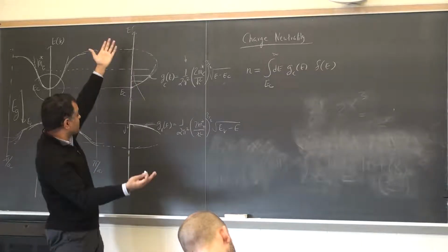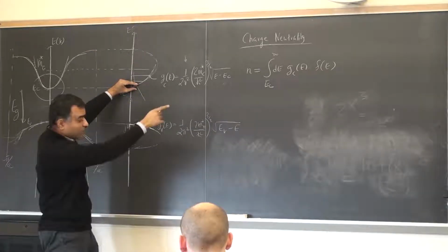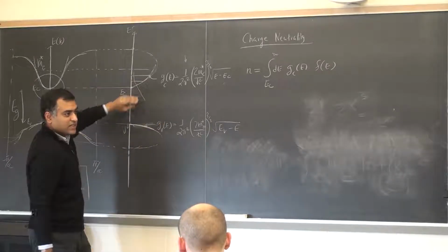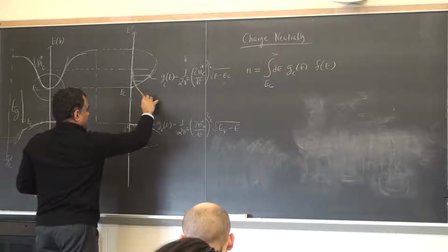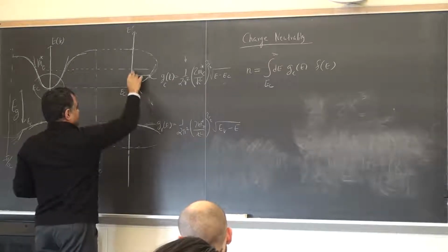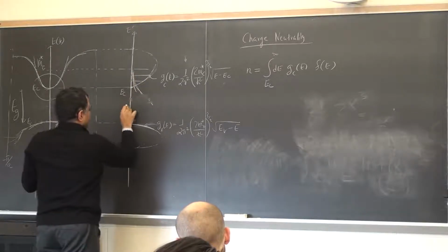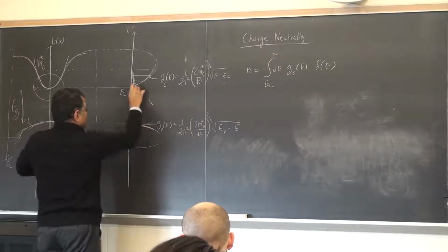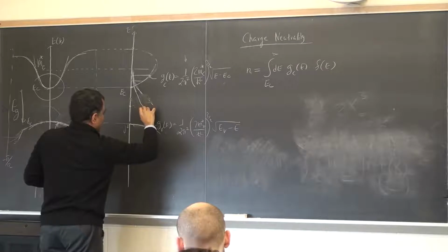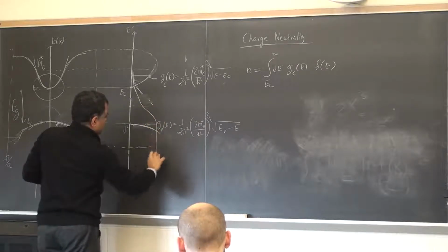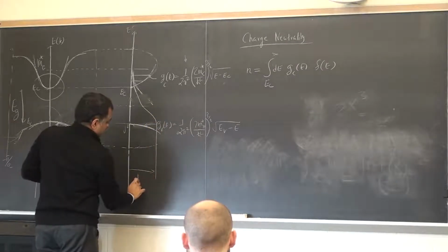If you have, for whatever weird reason, a very narrow band, then you can't put infinity. You must consider the top edge as the band. But I'm now going to show that this Fermi function is going to look something like this. Let's say the Fermi level is here. We don't know yet. We have to find it by charge neutrality. But let's say it's here. So it's going to be half, increase, and then kind of become 1. So that's 1.